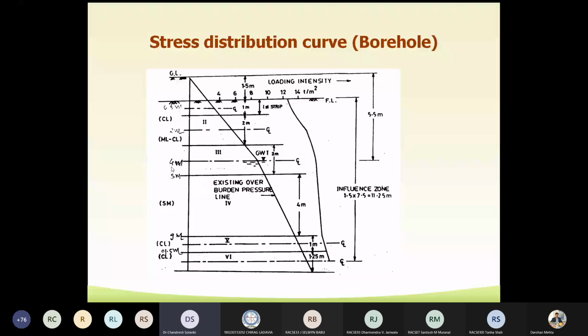In case of the silty sand, we are required to compute the settlement based on the N value. As the compression index Cc cannot be used for finding out the settlement of the sandy soil, we need to use the capital N value.